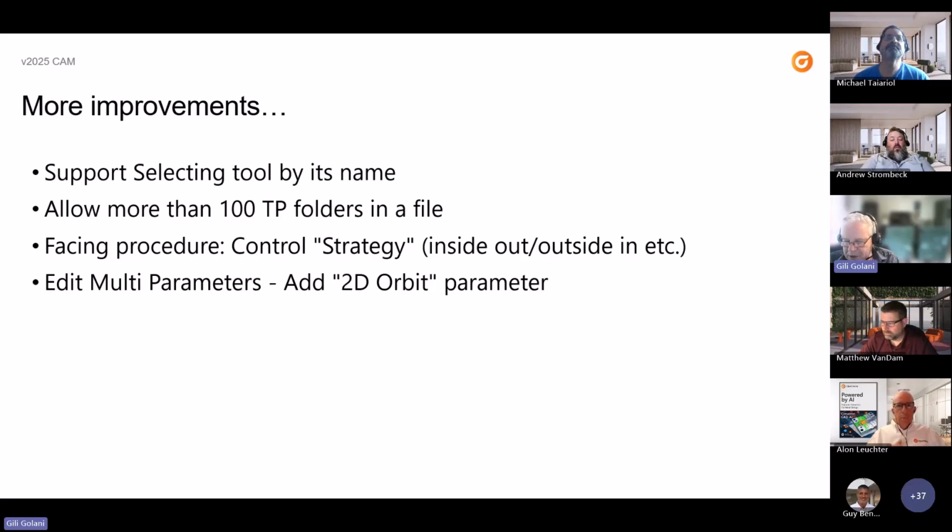This is not done here because we do not implement the entire procedure inside the motion editor. So the user defines exactly the radius and the type of the approach and retract he wants to do. We do it. If we fail, we make a message and we keep this connection open, and the user has to manually reconnect it in a different way.